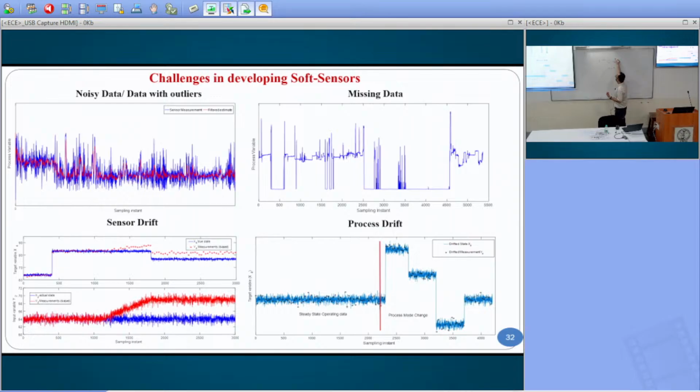This is coming from the plant every 6 hours, and these predictions are real-time predictions every time. So I take this error and I update it. Whenever the predictions are going bad, I'll update it actually. And there is a mechanism of when to update also. Sometimes there is no need to update continuously. If the predictions are coming close, I need not correct it, right? So there is a mechanism of when to update and when not to update also.